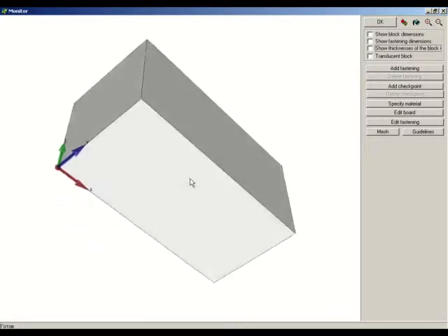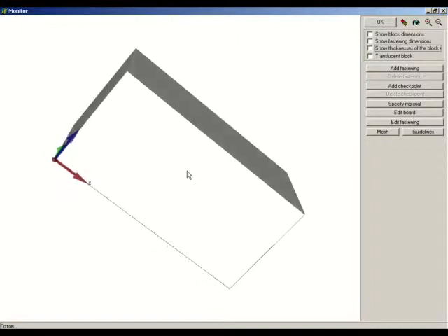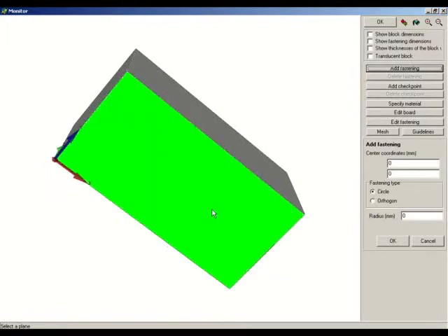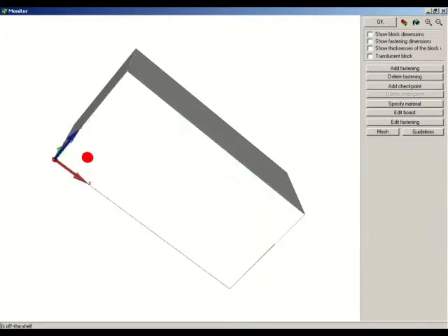So, and let's enter fastenings of the block at 4 corners from the bottom. So we allocate the fastening plane. We enter radius of the first fastening point equal to 5 millimeters. So we enter the coordinates. So 20 millimeters on X, 20 on Y. So similarly, we entered 3 other points of fastening.